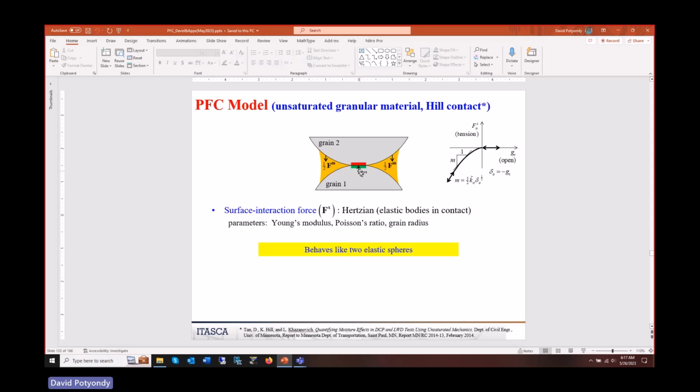So if I asked you, how would you solve that problem? Two elastic bodies pressed together. Well, you would probably say I'd buy a finite element program and I would make an elastic body and another elastic body, and I would push them together and measure force displacement. That would be one way to do it. He didn't have finite element programs, of course, so he had theory of elasticity. And of course, the other thing you have to answer is, if you're going to press two surfaces together, what's the shape of the surfaces?